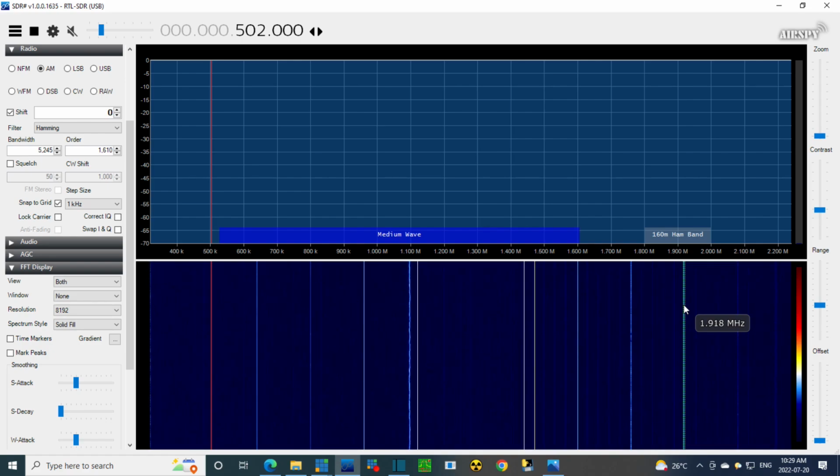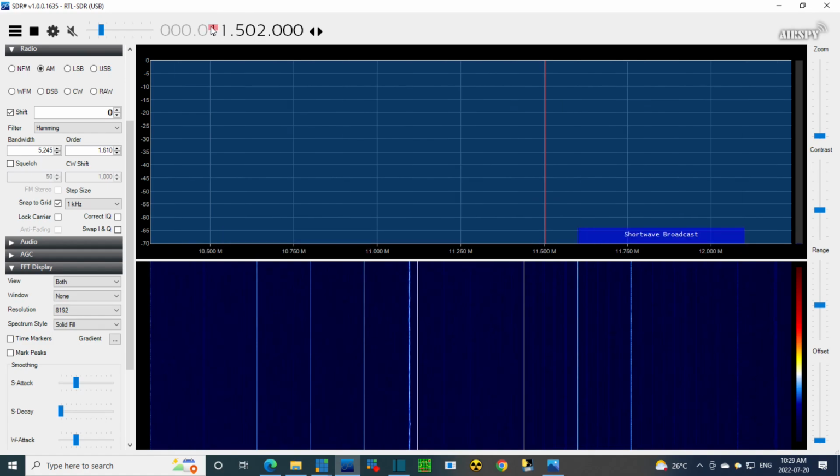It's no big deal. So we're leaving the broadcast band. First we're going to another band. So you see the local oscillator has just come to an end here because it's running at a different frequency. Now I'm going to tune in to 10 megahertz again for easy calculation. What's 10 megahertz plus 455? That would be 10,455.